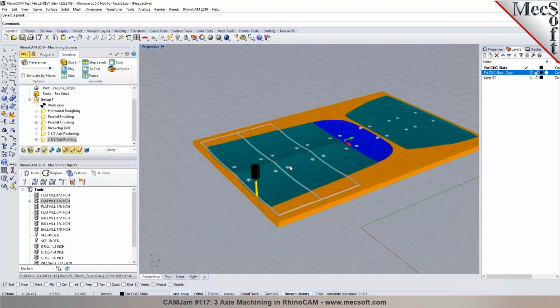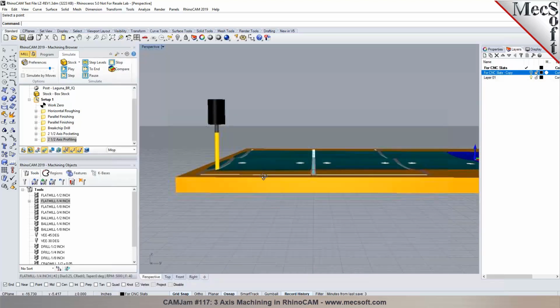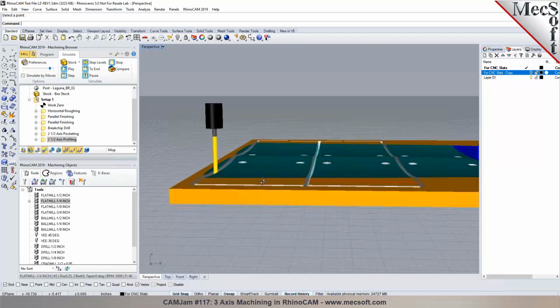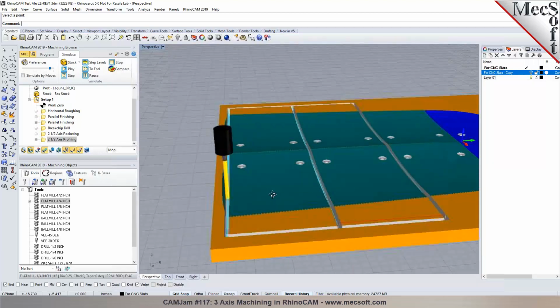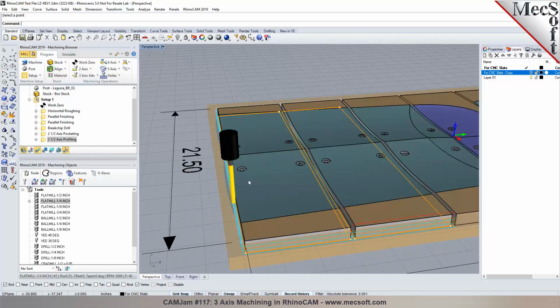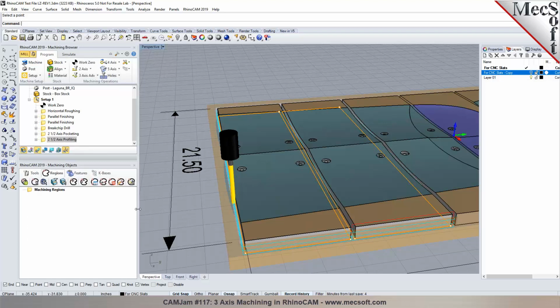And so what I ended up doing, I mean, I would draw this differently, is I selected all the odd slats, and then I just did the sides of the other 2 just to save on machining time. You could do that. Now, one of the other ways I would do it, probably, for the bridges and tabs, is being able to pick bridge point locations exactly where I wanted them to be placed.